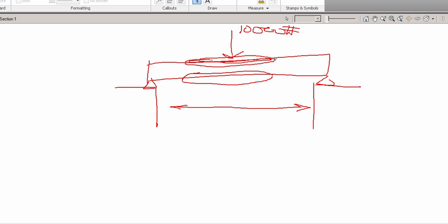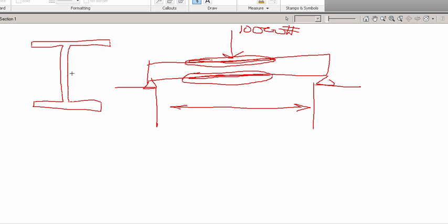This, right in this zone here, and here is where the greatest stresses are going to be. And if there's great stress, that means we need to have more material to resist that stress. Therefore, to compensate for the problem, we have a really thin web. Again, the web is this section right here. And we have really, not so much thick, but wide.